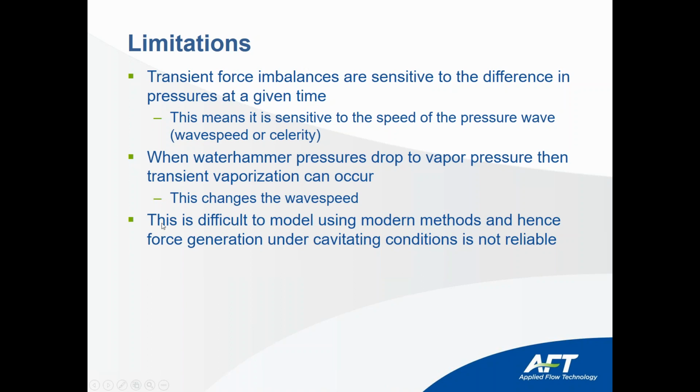So we suggest that when you're doing the study, if you see cavitation while calculating the forces, please turn it off, because the bubbles will distort your results, and it will not give you accurate results.